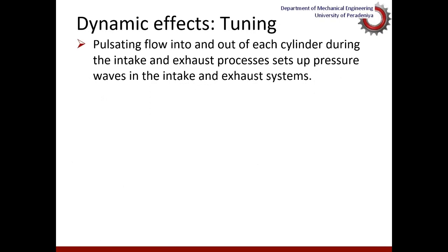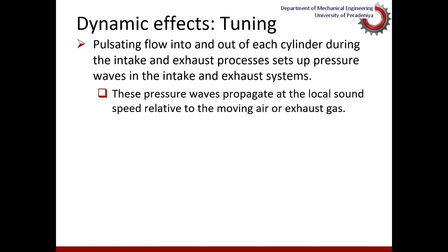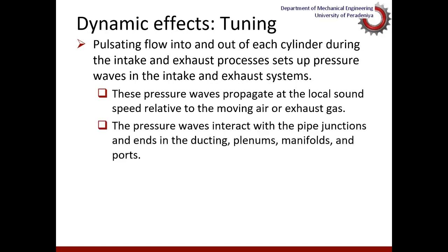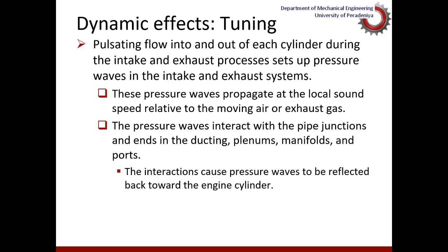Intake or exhaust tuning is due to something called pulsating flow into and out of the cylinder during the intake and exhaust process. So it's a pressure wave generated within the system, which creates a pulsating flow. That can be inward and outward flow, and it can sometimes be positive and sometimes negative, depending upon the directions of the pressure flow.